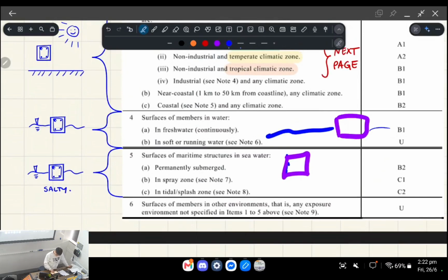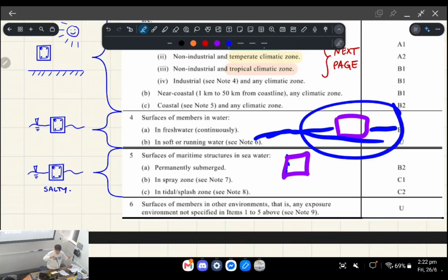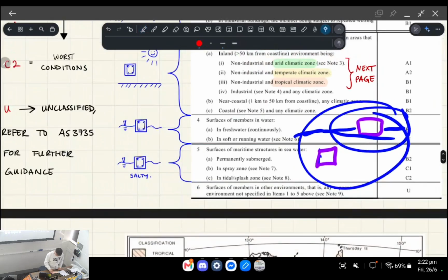So why do you reckon that is? It's because the process of corrosion essentially relies on oxygen, right? And so if it's starved of oxygen, like when it's permanently submerged, you don't actually have to deal with the same conditions for corrosion as you do if it's constantly getting exposed to oxygen. Do you know what I'm saying? Yeah. But it does have moisture ingress for both cases though.